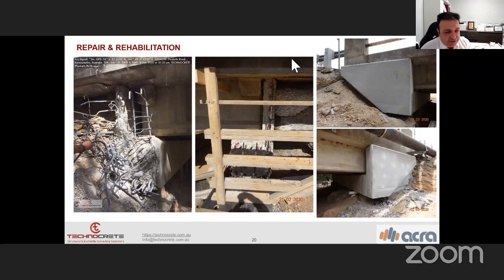Then in dam structures, the defects are a little bit more complex. I mean, we need more site information, but as a general thought, in water retaining structures like water tanks and dams, the first deterioration mechanism is soft water attack. Because the amount of calcium ion in soft water is very low, it can dissolve the calcium hydroxide available in the concrete. And then after some time, we will see deterioration of the concrete surface, aggregate exposure, and then the matrix around the aggregate, and then the aggregate falling. This is the consequence of soft water attack.